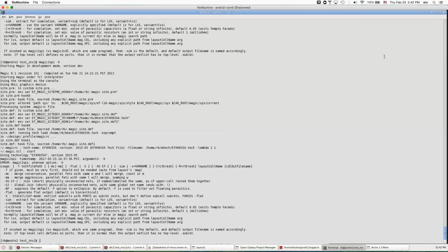Certain tools in Open Galaxy, in the project manager, do a real path on the PDK directory, so it resolves the symbolic link, and you end up seeing /dev something or other in front of it. But that should not cause any issue anywhere. You might see that from time to time in certain log files, but it doesn't cause any problems.